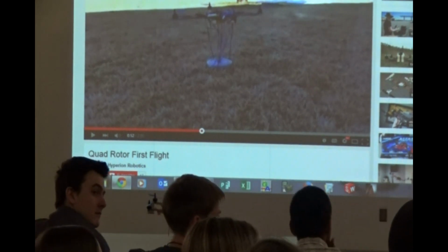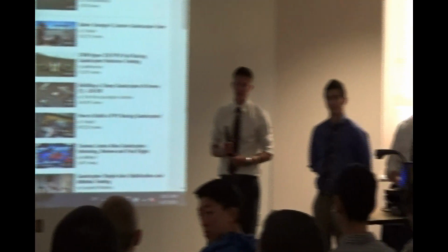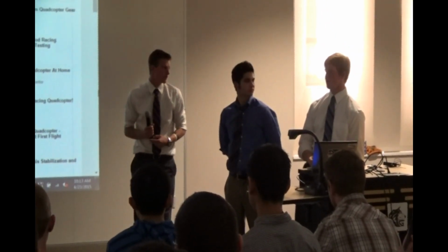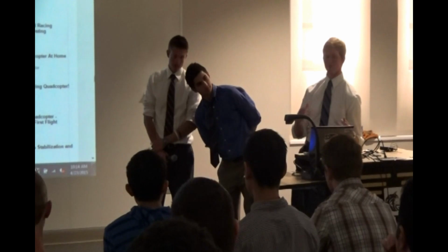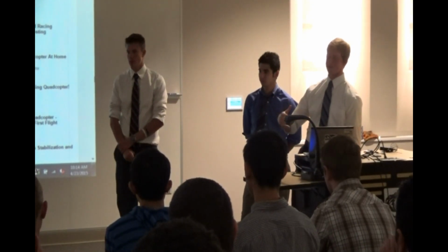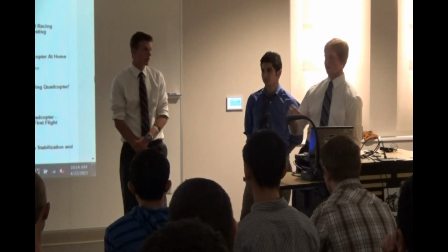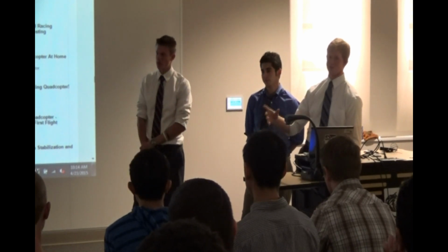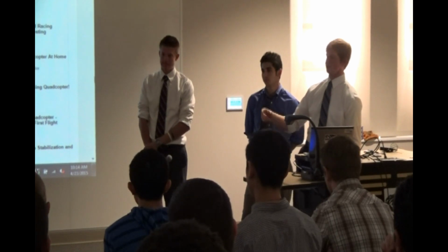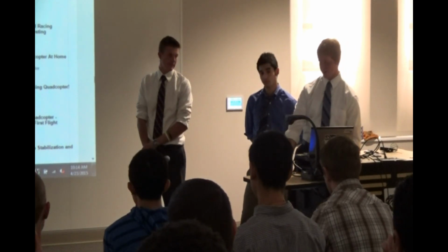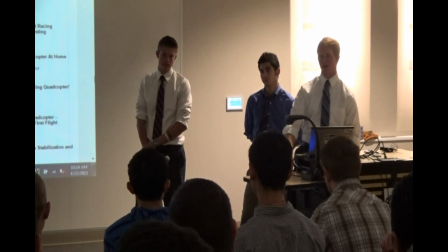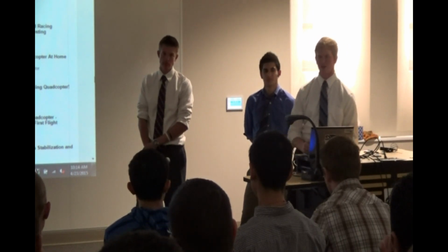Talking about the camera, if you put a camera on, would you need to add another battery, or is there enough power in that battery to also power the camera? There would be enough power. It would just be a matter of stepping down the voltage. The ESC has what's called a battery elimination circuit, and that gives out 5 volts, which we figured we'd be able to use to power microcontrollers. The Arduino Uno is the main microcontroller that we're using, and it would be able to supply power to any extra sensors, cameras, things like that.